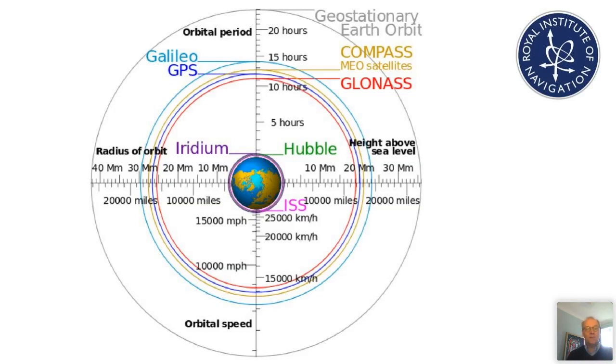And this is a wonderful discovery because it allows us to have fixed antennas on the Earth that will always be pointing at the satellite that we've peaked those antennas up at. So that's why you can collect Sky satellite TV, for example, on a fixed dish, because that dish is pointing at a geostationary satellite above the equator. And that's a very crowded bit of real estate, as you can imagine. So that's 36,000 kilometers, 24-hour orbital period.